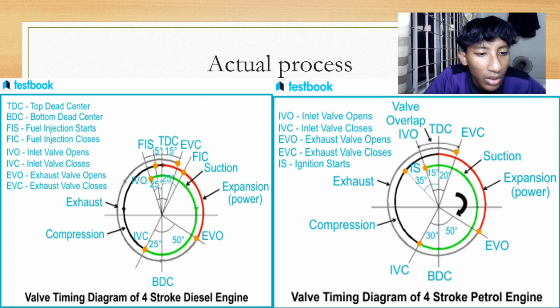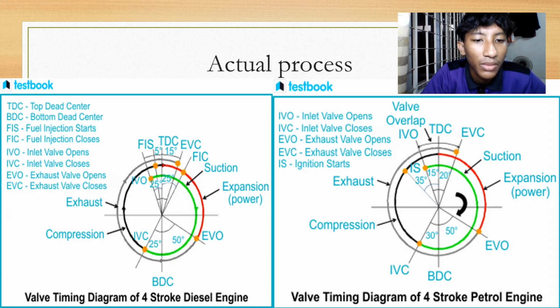Within the compression stroke, as the piston progresses towards TDC, fuel combustion occurs roughly 20 to 35 degrees before reaching TDC. This timing ensures proper fuel combustion and optimal propagation of the flame. Following combustion, the expansion stroke commences. This stroke is initiated by the release of pressure inside the combustion chamber due to the full combustion, resulting in the rotation of the crankshaft. The piston moves from TDC to the BDC during the expansion stroke.